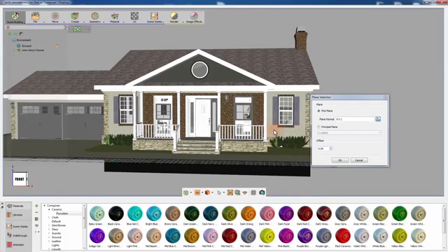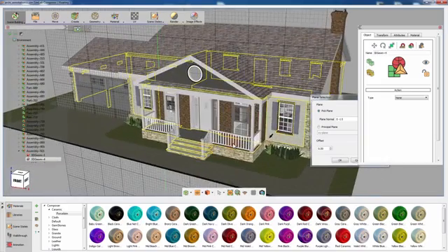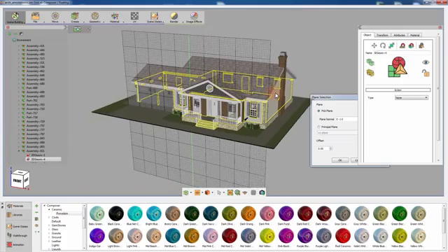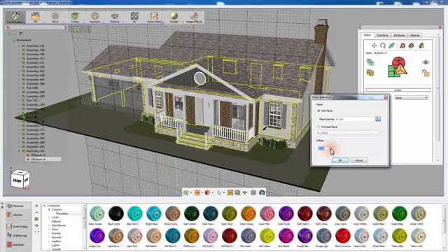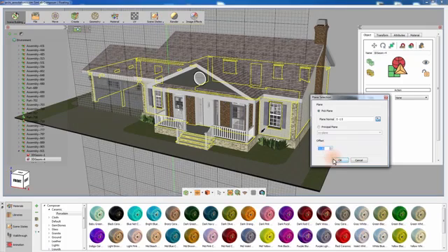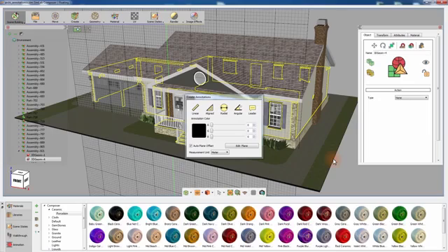Click on this wall and notice that a blue arrow has been created in the place of picking, indicating the normal of the plane you selected. Notice also that the grid has been rotated to match the plane you selected for annotation creation. Aside from picking a plane from the 3D area, you can determine the plane by selecting one of the principal planes in SimLab Composer. You also have the option to offset the plane you have selected parallel to its axis. Click OK to set the plane and initiate the Annotations Creation dialog window.